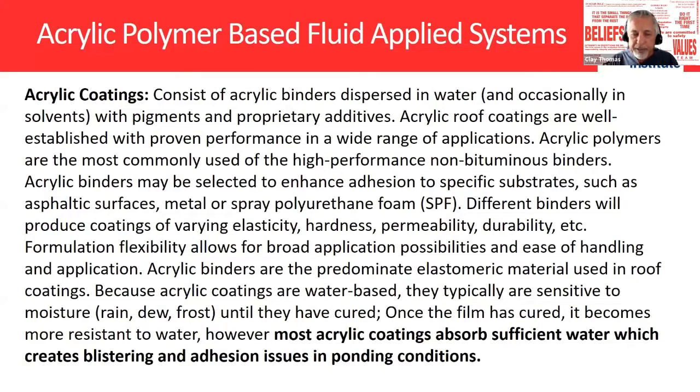So again, different types of coating. We're talking about acrylics. Acrylic binders dispersed in water and occasionally solvents, pigments, and proprietary additives. Again, they use a lot of acrylic coatings, but acrylic coatings are sensitive to ponding water. So you want to make sure that you have good drainage whenever you're using an acrylic product.